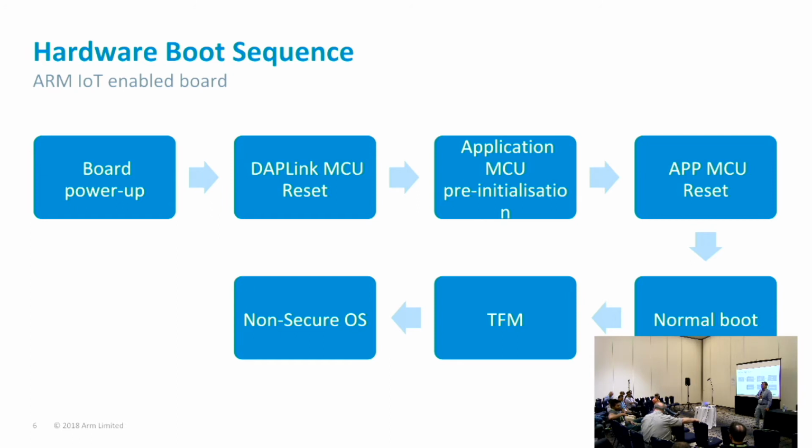So I guess that's the scenario you're talking about. Usually, you would implement something in the software which will disallow burning the OTP until you have switched the device from the development phase to the production phase. So you can still do the firmware update. You can, without really burning out the OTPs, still download the new firmware. But at that time, you know the device is in the development phase. Once you flip the device into the production state, there's only a limited set of things you can do.